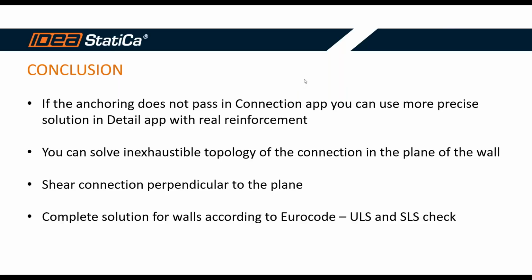Okay, thank you, Lukáš, and also thank you for the interesting presentation. So what are the conclusions of today's webinar? One of them is that if the anchoring does not pass in the connection app, you can perform a precise and advanced analysis in the detail application, which considers the reinforcement in the wall to check your cast in situ walls or other concrete details.